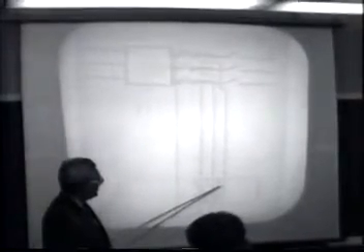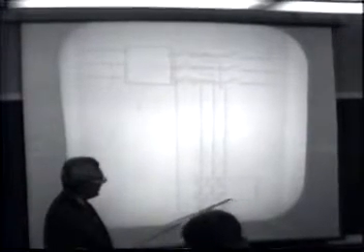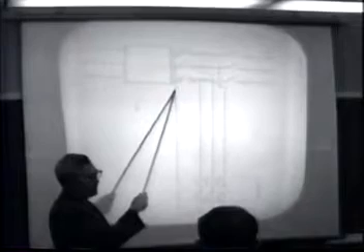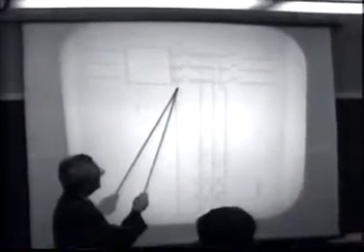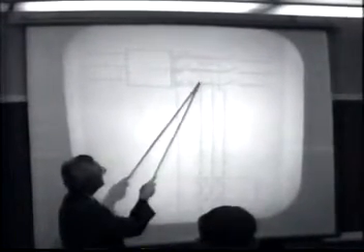We've shown here a two-element meter through the current element of the var meter. You note we come down here back through this path through the closed contact, through the ammeter, back around here through the other closed contact, and back this way, completing the circuit. So you have a complete electric circuit shown there. In this particular one, this one is not switched onto the ammeter, so you can follow the path through the elements of the watt and var meter, through this closed contact and back, making a complete current circuit there.